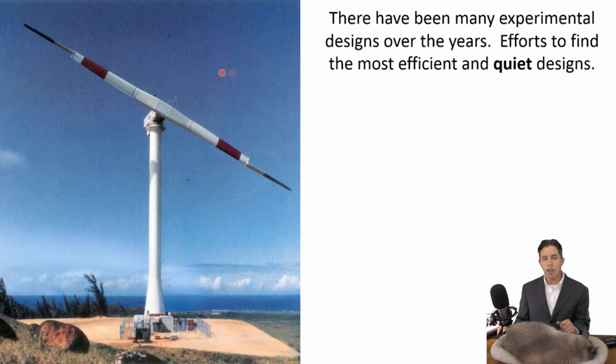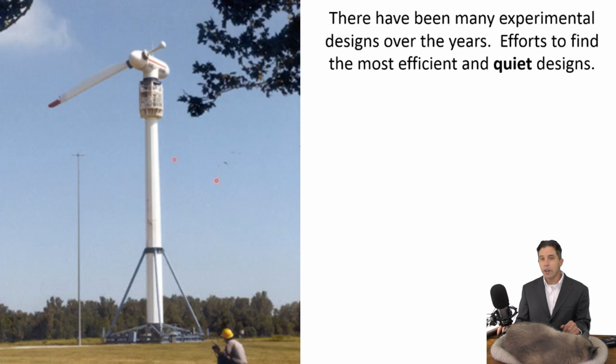So talking about sound first, California was one of the first states to really adopt wind technology. They did a lot of experimentation in California with different windmill designs. And it's true, the first ones were really noisy. They spun really fast, they made a lot of noise. So they experimented with some different designs. Here's a 2-blade design. Here's a 1-blade design, which looks kind of funny. It's got a counterweight on the other side so it doesn't shake itself apart.